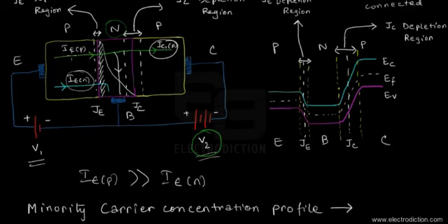The current from the emitter section reaches the collector section and enters a region of higher resistance, since the collector section has lesser doping than the emitter section, and due to the greater width of the reverse biased collector junction, the resistance across the depletion region in the collector junction is quite high compared to that across the forward biased emitter junction.